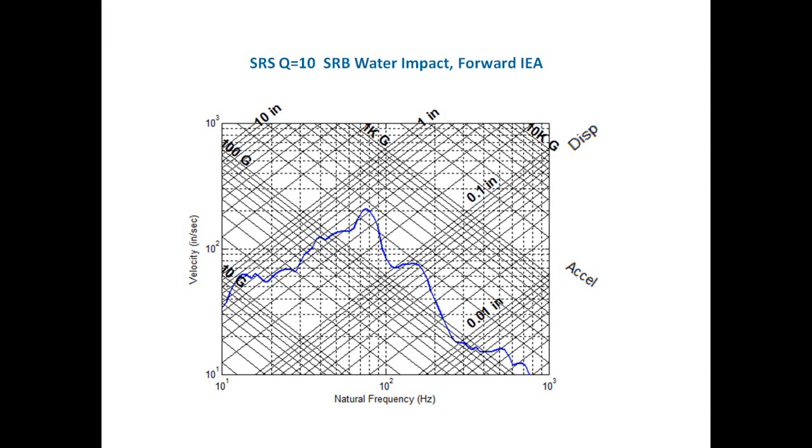So according to that Mil-Standard 810E rule, and depending on whether we're considering 50 inches per second or 100 inches per second to be the threshold, for the case of a 100 inches per second threshold, we're about 6 dB higher, and for the case of a 50 inches per second threshold, we're 12 dB higher. So all of that is telling us that this was a severe shock event, and the effect of that shock on that avionics box needs to be considered accordingly, especially since that avionics box is going to be reflown on an upcoming mission.